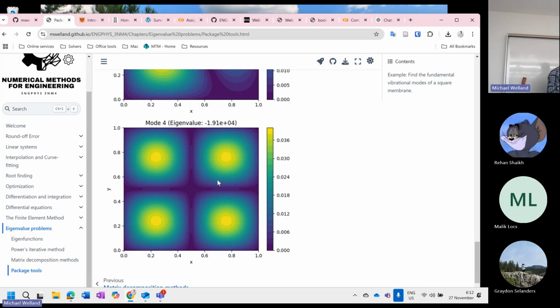What's that? Any kind of buckling. For example, stability analysis. We talked about von Neumann stability analysis, where little numerical noise kind of cascaded and had positive feedback to break it down. Same thing is true of a pillar under load. And that turns out to be your stability is related to your smallest eigenvalue. So what that means is if you just poke it a little bit, if that eigenvalue is positive, it's going to reinforce and your pillar is going to buckle. Buckling is an eigenvalue stability problem.